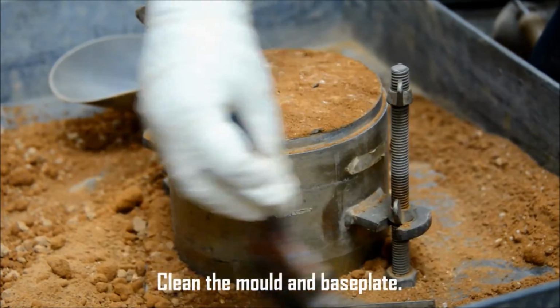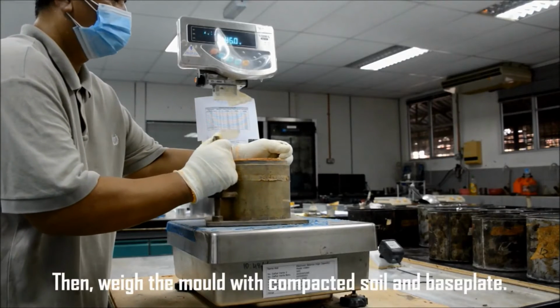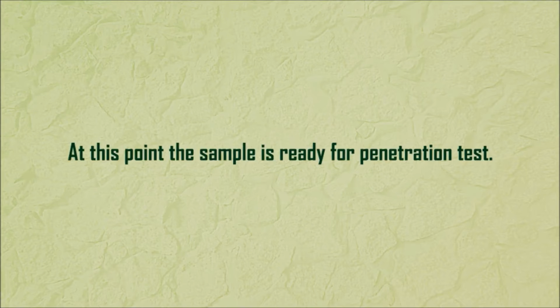Clean the mold and base plate. Then, weigh the mold with compacted soil and base plate. At this point, the sample is ready for the penetration test.